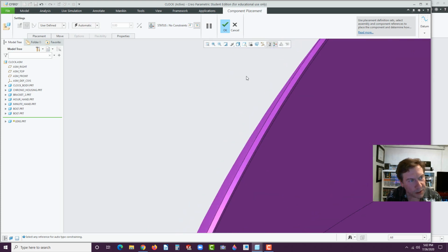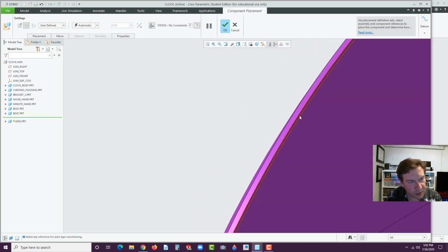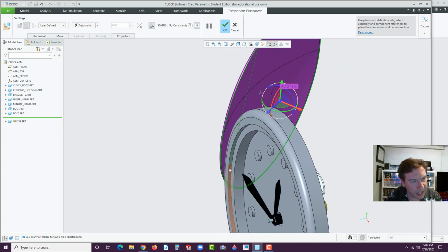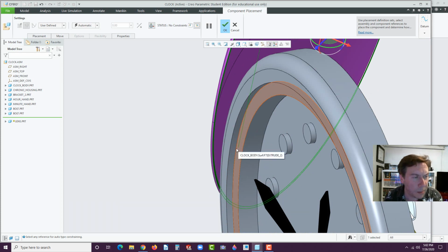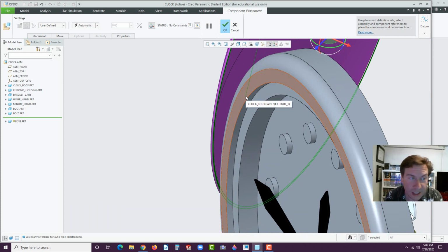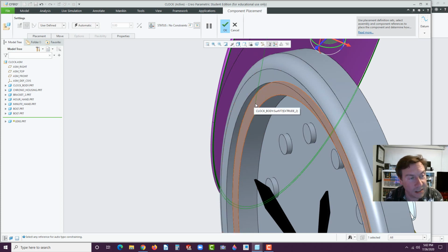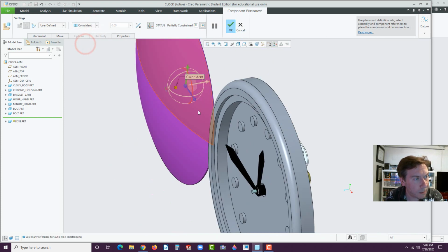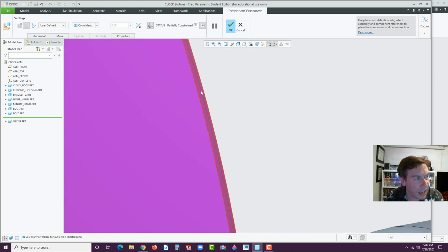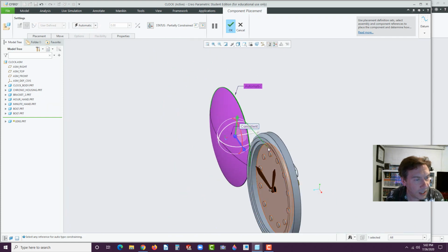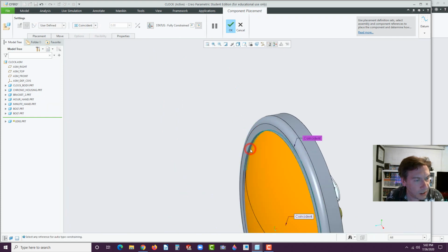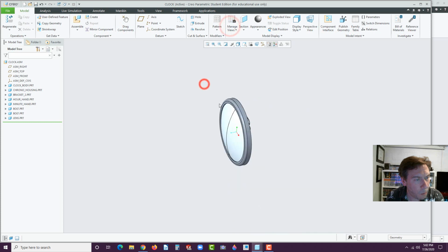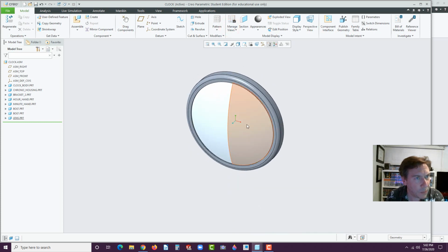Okay, first of all, you'll see there's two edges here. There's this flat edge. May as well mount that, and here's where the students start making mistakes. They select this face. That's not the face that's supposed to be aligned to. It's supposed to be in this recess. So the second face there. Now, if it goes at an angle, make sure you just go coincident. All right, and now this outside face right here to that face right there, and you got it. The lens is in place.